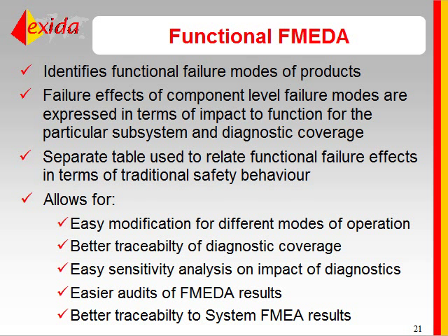The functional failure mode is the most basic type of FMEDA because, like an FMEA, the functional failure modes of the product or an instrument are identified depending on the functional failure modes of the components. If you've got a pneumatic actuator, for example, and the diaphragm bursts and the pressure is vented, the spring will move that actuator to its fail-safe state.